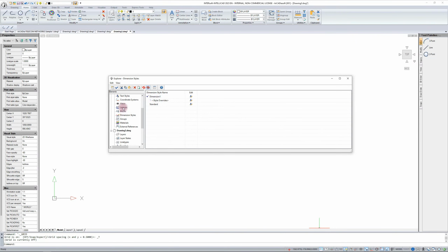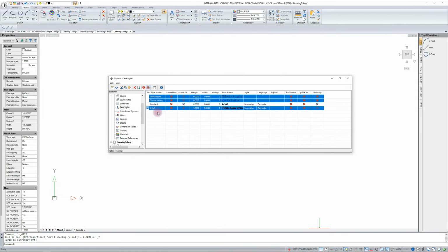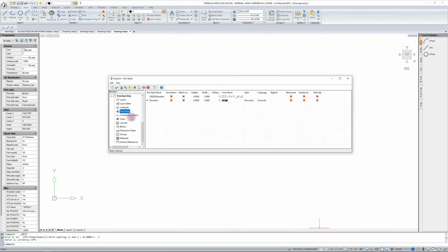If I had any text, it's the same. That's how I copy and insert text into the drawing. Paste. I can, as I mentioned before, define layers for myself, instantly giving them the color, the thickness of the line, the types of those lines, and then I don't have to define it every time anymore.